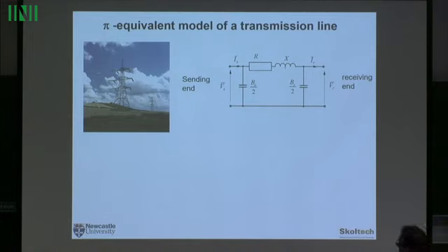Now why does it have inductance, first of all? If you look at those wires, there are no coils on them, but those wires are quite close to each other, and the magnetic field around each of those wires, and the interactions between the magnetic fields of those wires, will cause this inductive effect. There are different phases, deliberately close to each other.